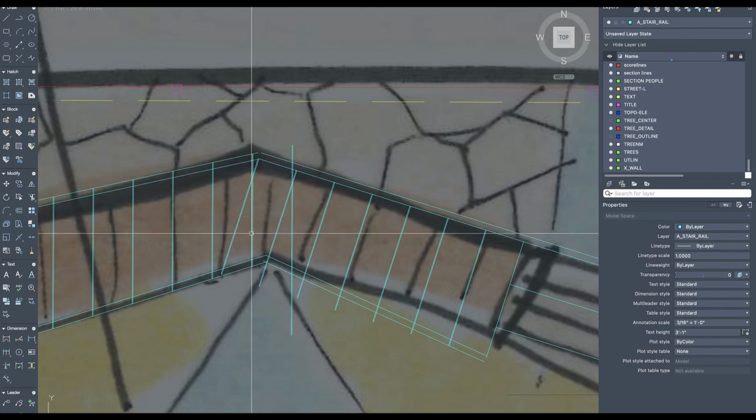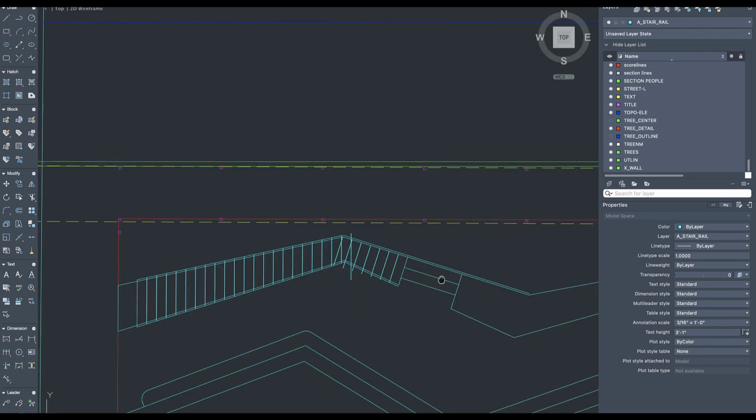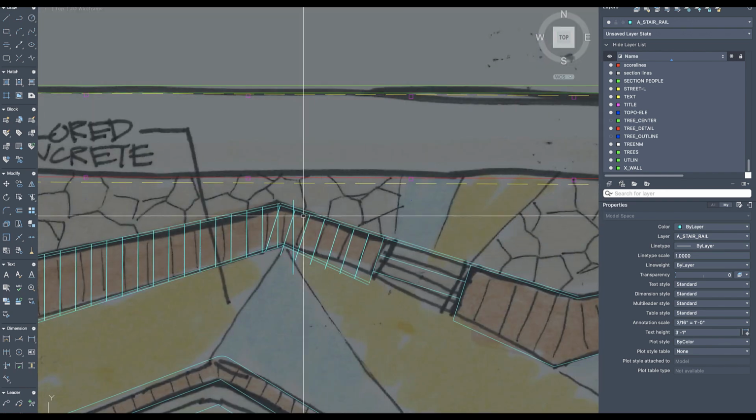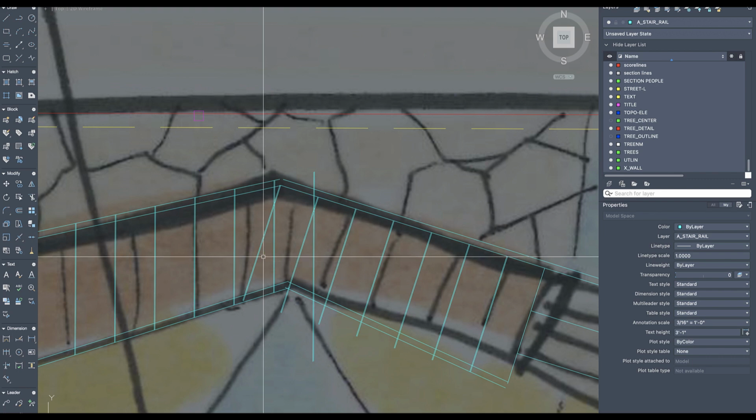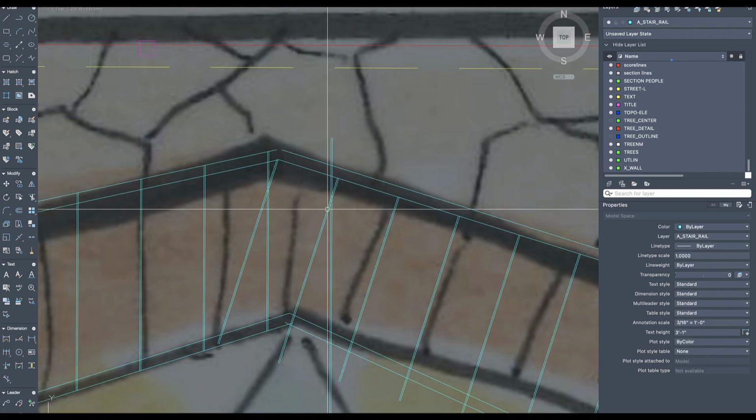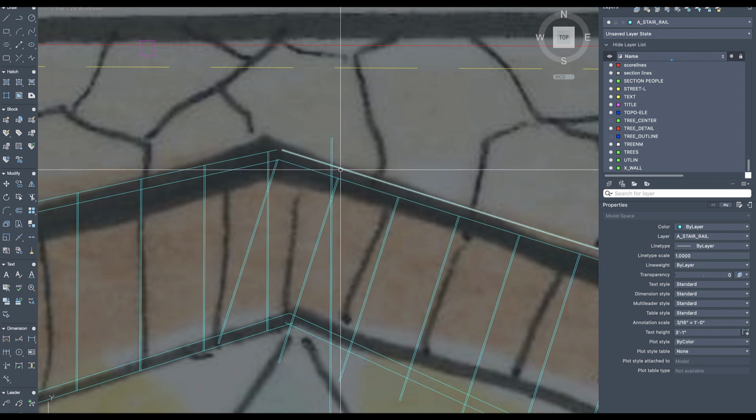I'll tell you that the way that it's designed, I probably want to consider whether I need to move this line over, extend these stairs over a little bit, sort of move them off the design. I think that might be the right idea, just because I'm going to get some funny cuts in here. This board might come here, up, over, flip back, and cut back this way and become an odd shape. It's going to be bigger than 12 inches wide because we've got to get this little blip in here. It seems like a fun cut. I actually think I'm going to leave it exactly like that.